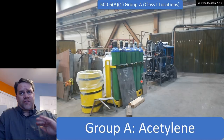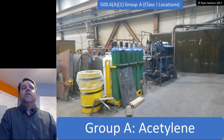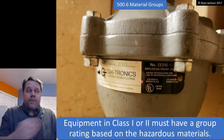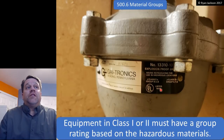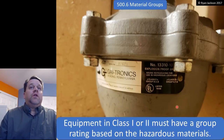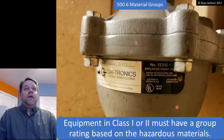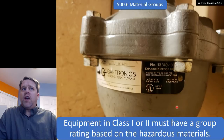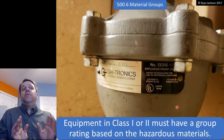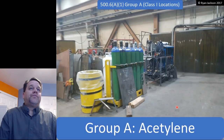So acetylene is treated as its own little animal, Group A. Now, looking back at this piece of equipment, it's suitable for groups B, C, and D. I cannot put this light in a Class 1 location that's hazardous due to the presence of acetylene. That's fine. I'm not in an acetylene-enriched environment, so I'm okay. But if I was, I would need to be very careful indeed that my equipment is rated for Group A.